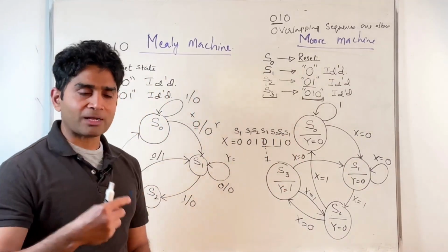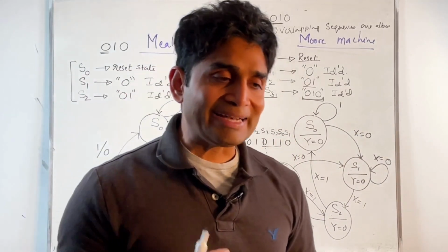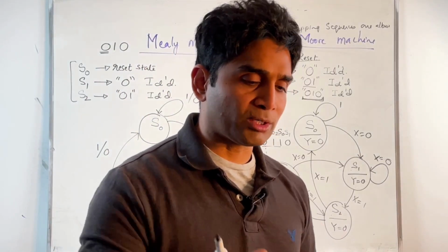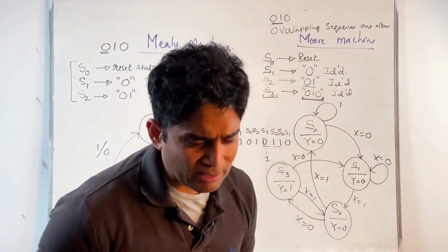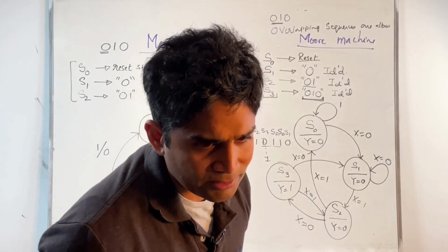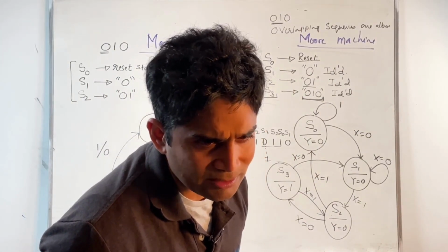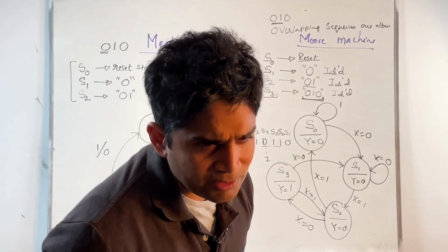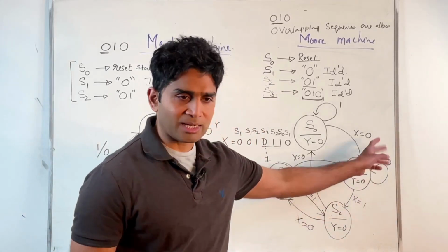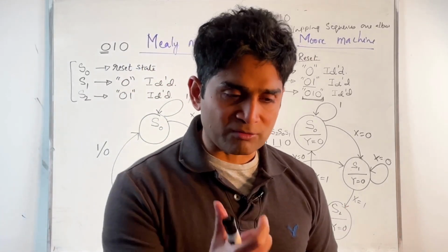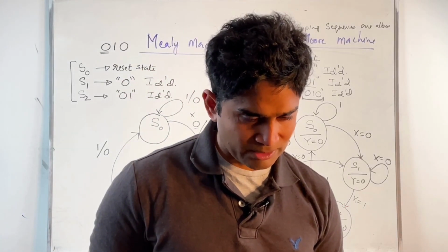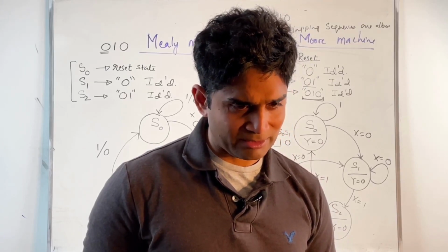So you can run the sequence, validate it by running this through your state diagram, and make sure that it actually works. Does that help, Fletcher? Is that what you're trying to say? So S1 goes back to itself when there is a 0. That's correct, because I discard the previous 0, start counting the new 0 as the start of my potential sequence. Does that make sense?